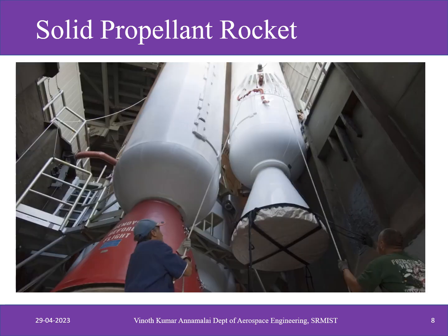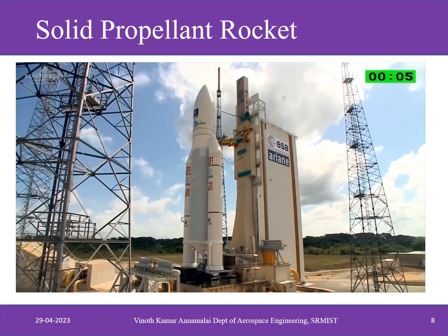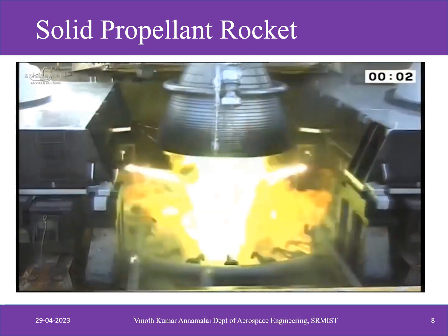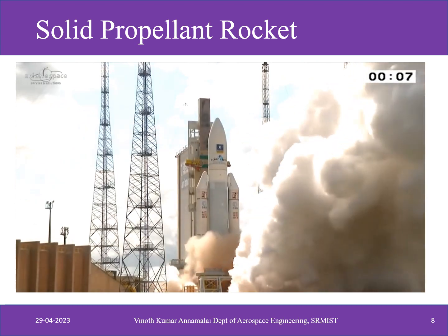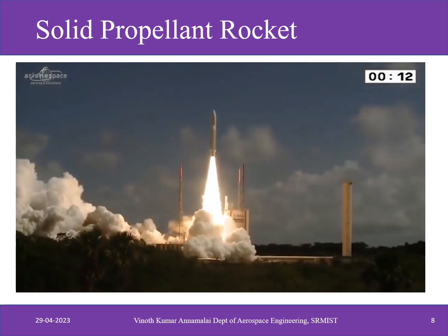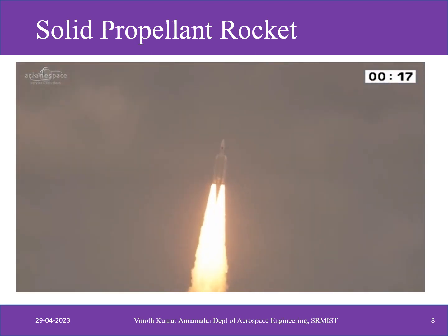The Atlas V boosters have a diameter of 1.6 meters, which is large, but there's much larger. Here we have the Ariane 5 rocket, a rocket operated by Arianespace. Now we're no longer talking about strap-on boosters, because the Ariane 5 has to use these. These boosters have a diameter of 3.06 meters. One of these provides almost twice as much thrust as the Atlas V's first stage liquid engine does. Remember that motors provide more thrust than similarly sized engines do, so this shouldn't come as a surprise.